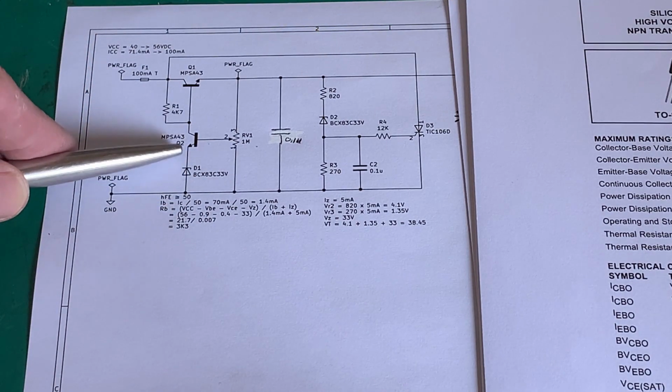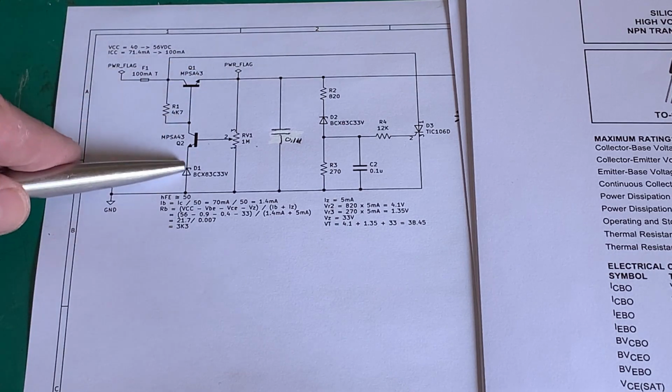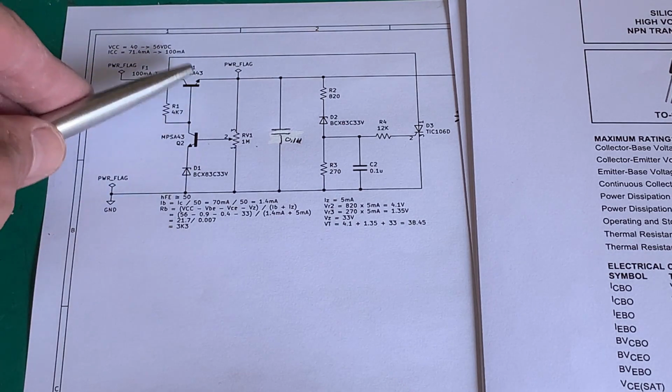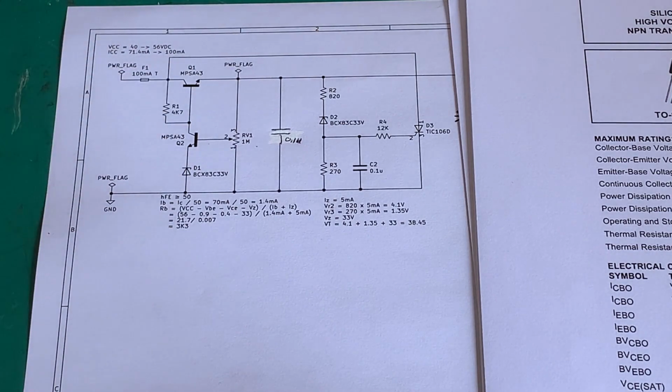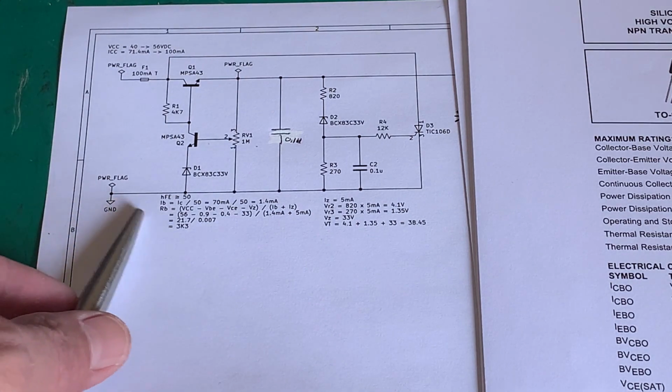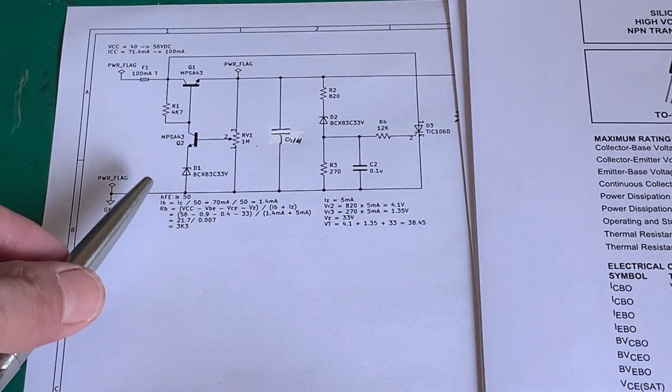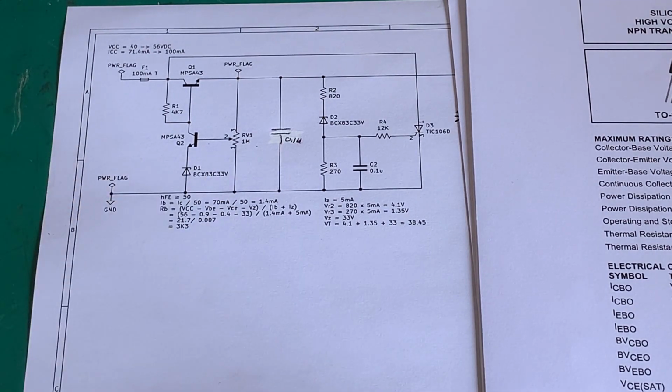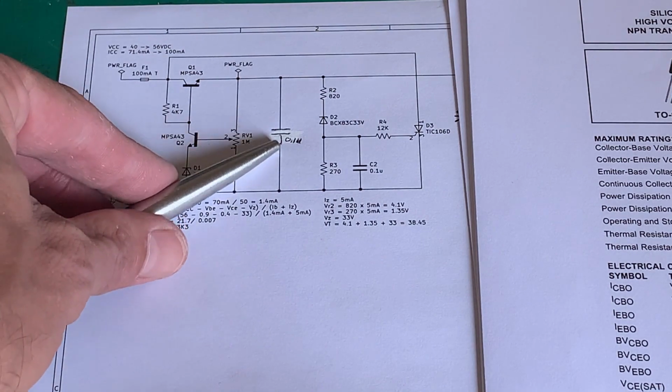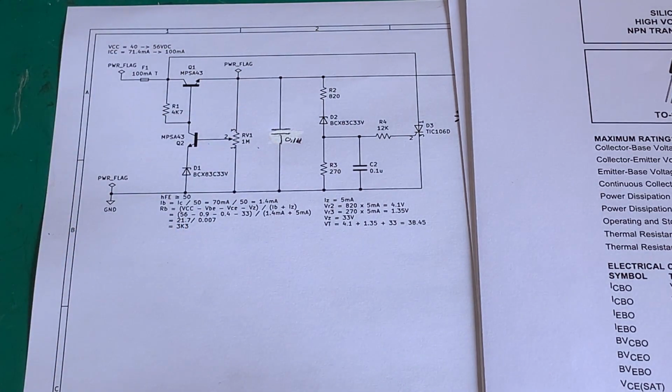how would I put it, the voltage there is always going to be that Zener plus the base emitter voltage. And of course, how we calculate it is in this formula here. The gain I've taken is 50, and I'll show you in the data sheets why. We've added a capacitor here, and I will show you on the scope why we're going to do that. But